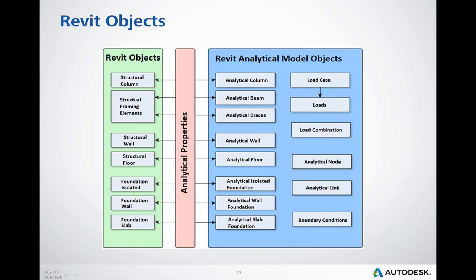Revit elements which can be exported, or created during import from Robot, also updated from Robot, are available as structural elements. But additionally, these elements need to have the analytical model enabled. As a default, it is enabled for all of them. There is a list of Revit structural elements in the green panel of this picture.